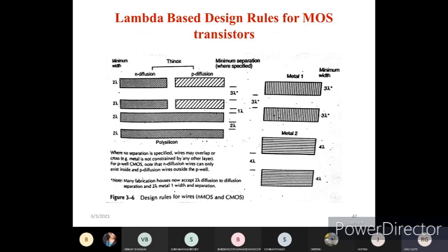And in order to implement, we will be using an NMOS transistor. In order to create this NMOS transistor, we will be using polysilicon. What length or width of polysilicon we need to consider also plays an important role. You can see the minimum spacing between N diffusion to P diffusion has to be 1 lambda, which you need to consider during the design procedure.